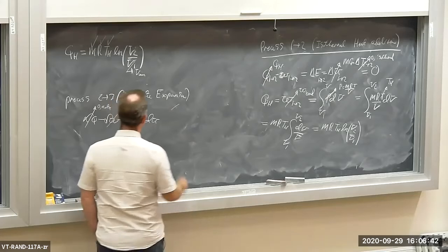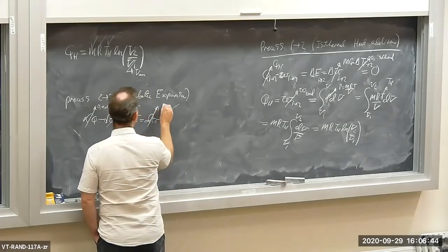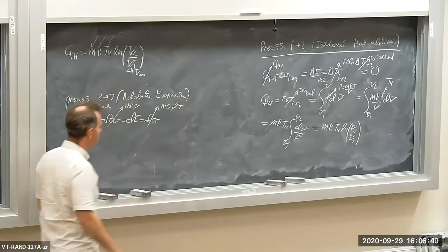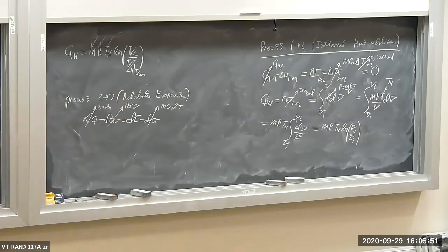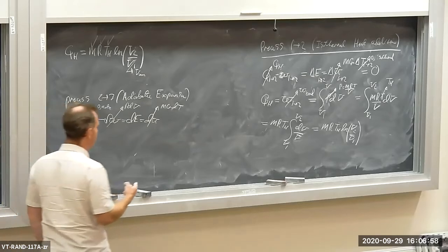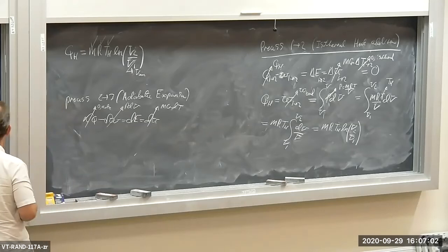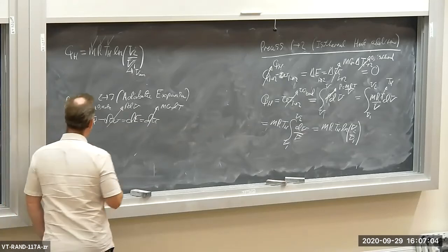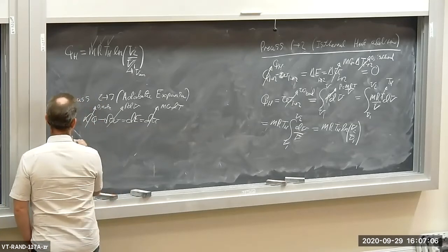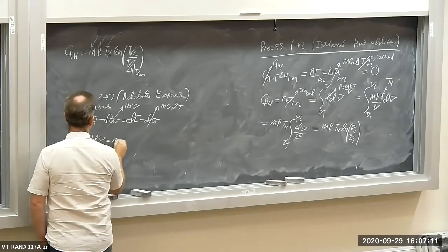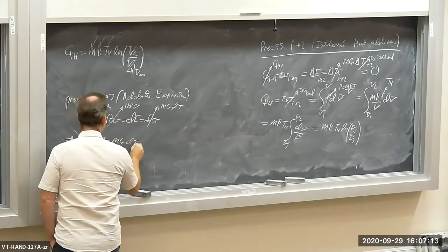Now, if we assume constant specific heats, then dU is equal to mCV dT. That's from the property relationship. dU is equal to mCV dT. That's internal energy, not specific internal energy. Notice everything's capitals in here, all right? Okay, so let's write what I got. I got minus PdV is equal to mCV dT.